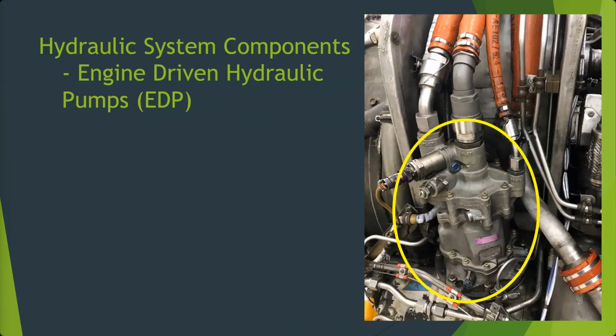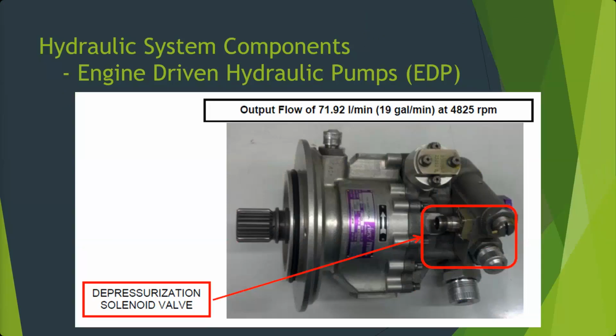So most of your accessories have gone to V-band clamps, and they're incredibly strong because you've got that tension all the way around. They're super, super strong. The weak point in them is this nut right here. It can strip if you over torque it. So hence the torque tap, torque tap. There you go. Here is another pump, more similar to the one I've got here.